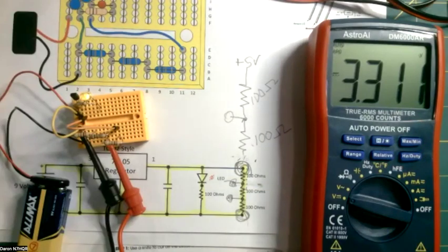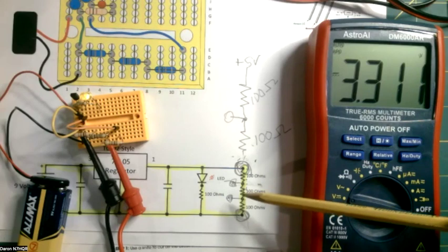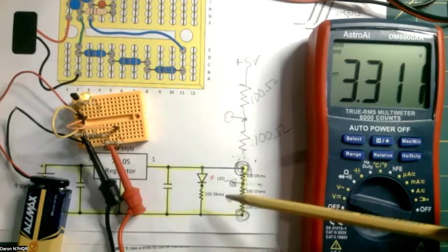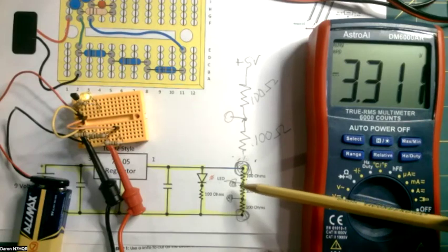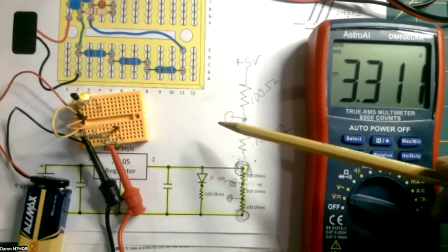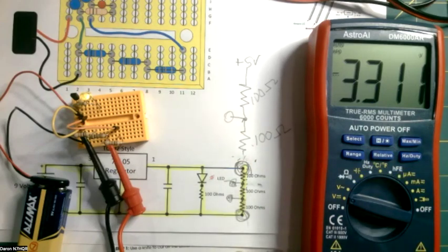And that's something Joe and I were talking about. These are great for reference voltages. If you need to have 8.6 volts as a reference to do something, this is a great way to get it. But once you start drawing current through there to do things, it gets a little more squirrely and a little more complicated how you put that together. So that would change the voltage division if you were to load whatever point you were testing it at.